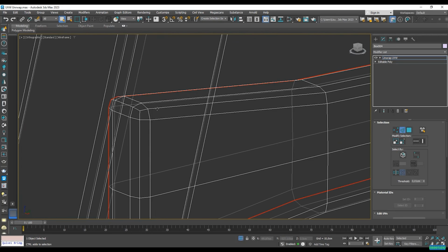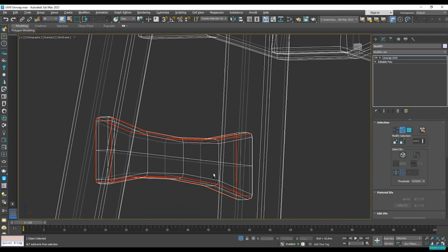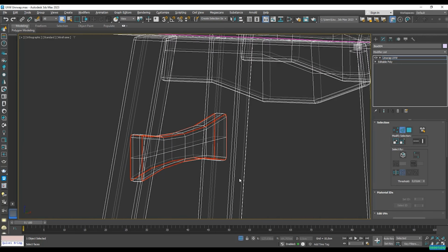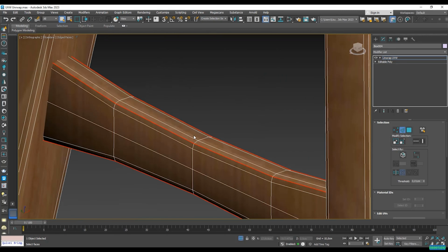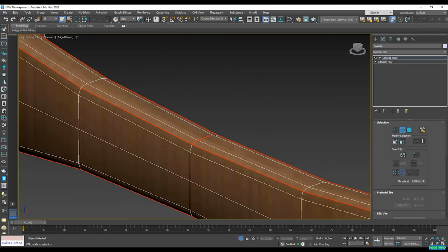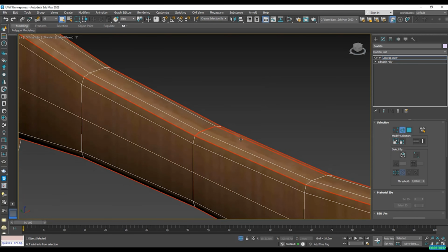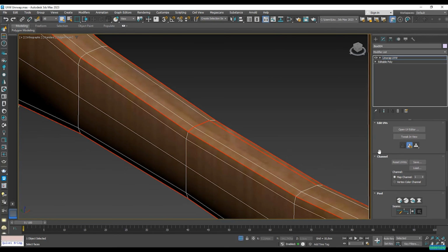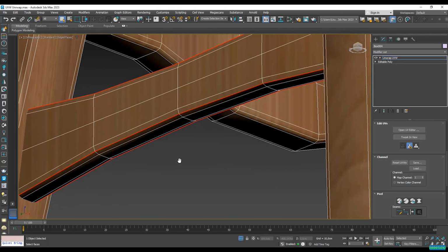Now the back surface. Make sure to actually leave this symmetrical. So I'm going to double click here and double click over here. Okay, so I have one face there, one face over here, and now the strip. Once again, I'm going to just cut it in here so that it doesn't leave me with a long strip there. And notice that I just made a mistake, and if I were using my peel mode, this would have been something very hard to go back to. So because I'm not, I can just unselect it with my Alt key. I'm going to now cut it through here.